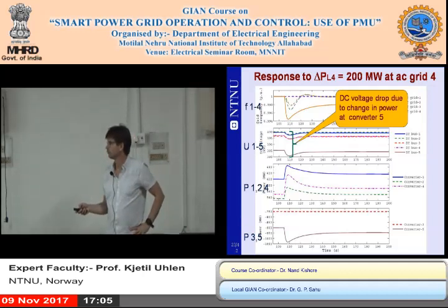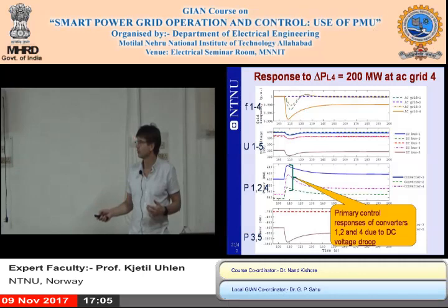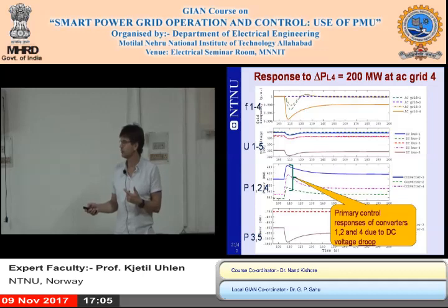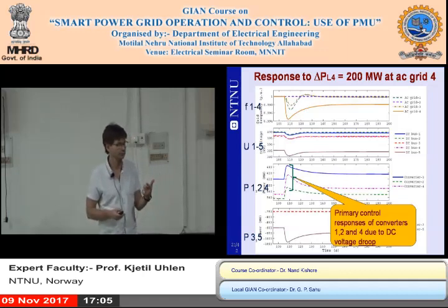And okay, what happens then? You draw more power out of the other AC grids. Well, then it's like an additional load. So then the frequency in those grids will also drop. So in this case, we have transferred some of the problem from one AC system to all the others that are equipped with droop control. So they help each other, even though they're not synchronously connected.